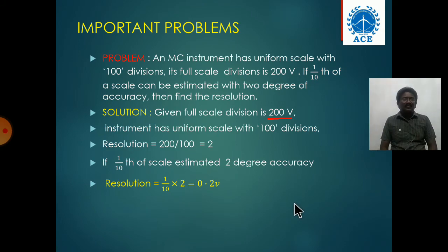Actually here the ammeter has one meter, one shunt resistance, one power supply and one switch also. With the help of the switch you can change the position of the current levels. That means every time you can measure different shunt resistances. So this is the multi-range DC ammeter.